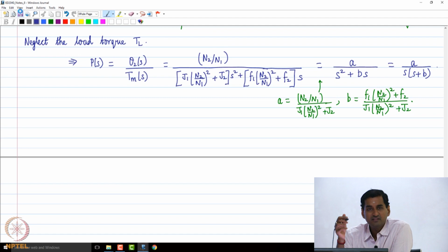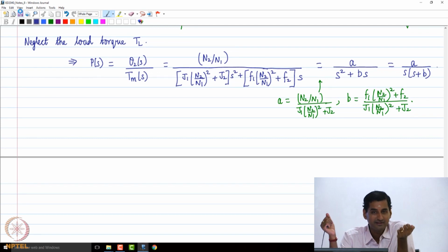No, right. Of course, it depends on how we look at it. As we discussed, some people call it critically or marginally stable, but we know that when we have a non-repeating pole at the origin, you give a step input, the output will become unbounded, right. You can immediately picturize it. Let us say you have a motor shaft and a gear transmission, you give a step voltage, you will see the output shaft will keep on rotating. You might have observed it even in your experiment on DC motor that some of you might have done, right. So, essentially the output shaft might have just kept on rotating, right. So, if you do not apply any control to the system, that is what is going to happen here.